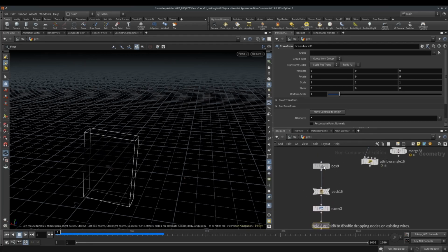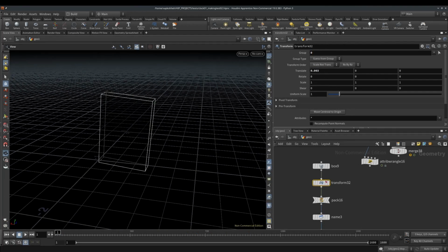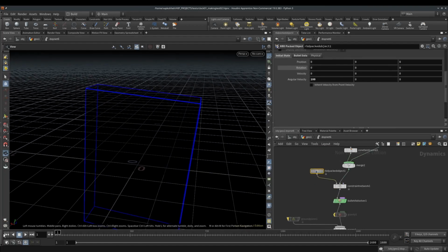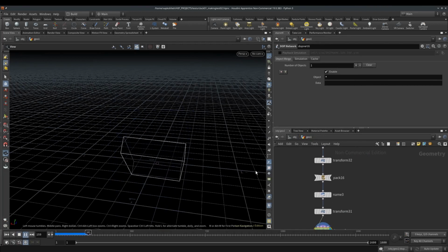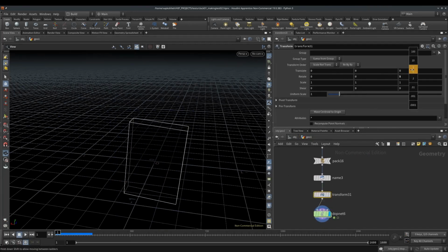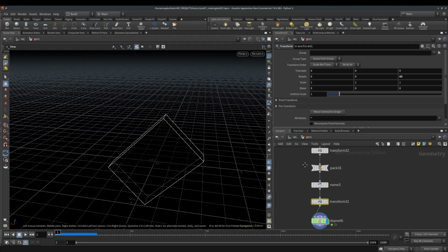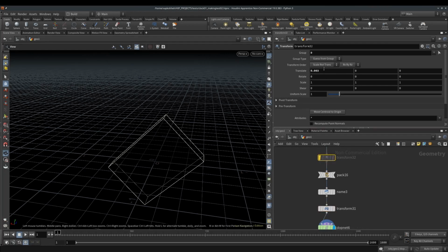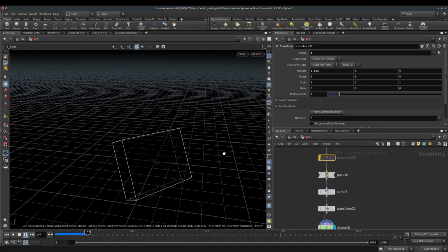And this works fine until I transform just one vertex of this box by a tiny amount. And now suddenly this doesn't work. And not only that, it does completely physically incorrect things. Things don't rotate like this. They don't conserve angular velocity, they conserve angular momentum. So it only understands this for perfect colliders like boxes and cylinders. If I delete this transform that makes it not a perfect box, you will see it starts rotating completely differently, as it should. This was a very disappointing discovery for me.